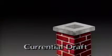Draft is the word we use to describe the slight suction that lifts the byproducts of combustion up the chimney to the outdoors. Natural draft is the result of hot gases rising. By putting the hot gases in a narrow, high chimney, the gases can be made to rise faster.